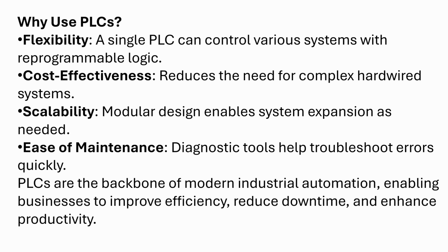And really, why would somebody want to use a PLC? Well, for one thing, they're pretty flexible. A single PLC can control a number of systems with reprogrammable logic. I mean, you can always go in and change a program to perform a new task. So if you've got to update or change a machine, it's much easier to go in and change a program in a PLC, as long as you have enough inputs and outputs to handle any new devices. Much easier than trying to rewire or add relays to a relay control panel. It was a lot more difficult many years ago.